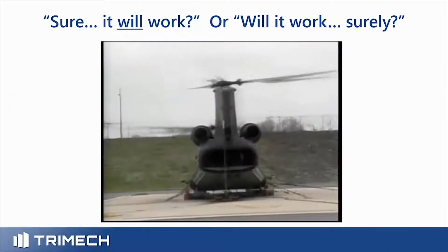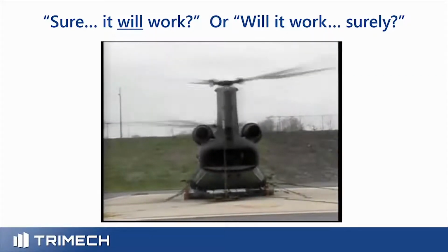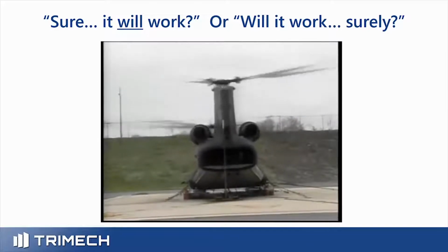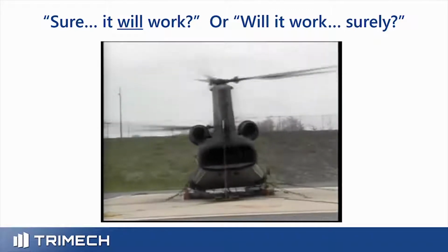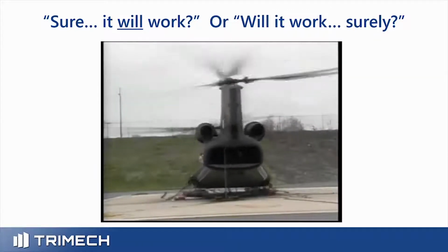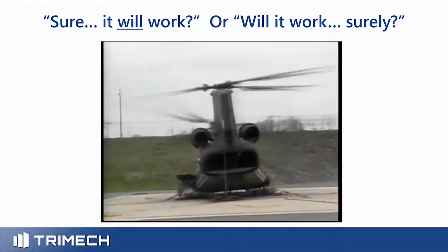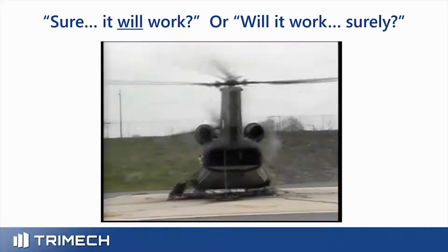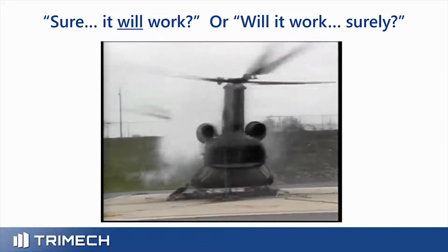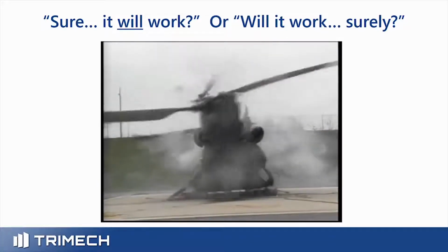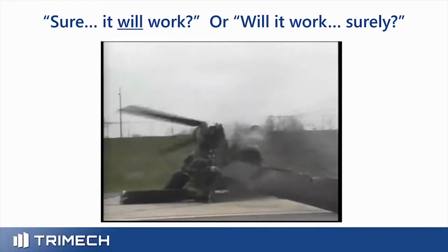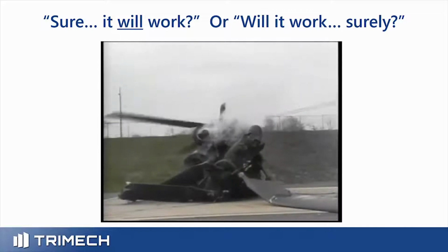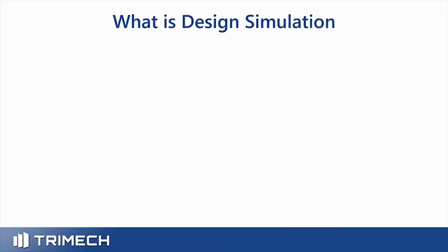And of course, it's always painful when something doesn't work, right? We can do as much checking as we can. We can try to really test things for strength. But in this example, we've got a helicopter. It's been tested for strength. It's been tested for flight hours, but something wasn't taken into account. Probably a frequency analysis wasn't performed to see that some of the structural integrity of this would vibrate at a fundamental frequency that matched the motors in the helicopter. And it does not go well, right? Even if this is budgeted into your schedule, a result like this is painful. We don't want to be responsible for something like this happening, right?